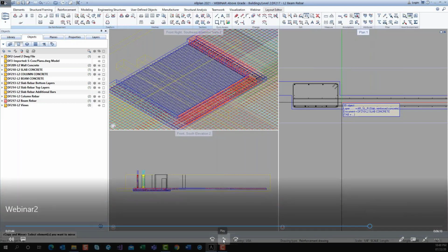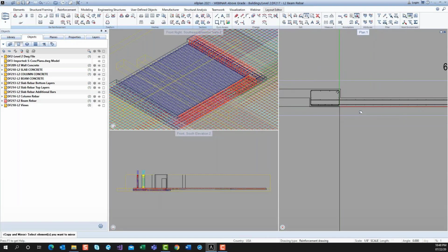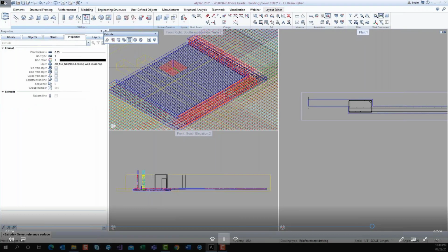So now, as I said, the contractor was called up. He says, you know what, Dave, sorry about this. It's either I've got a crane opening going in, or I have an opening in this slab. What can I do? Well, if it was the area reinforcement tool, I would have the ability to add the opening after the fact. But because this is our general tool, I'm going to show you, I showed you the trim bars command is trimming on a line. I'm going to show you how we trim to an opening, all 4 layers of steel in one shot. It's one of the very rare instances I have seen a software do this. I've seen other softwares try and attempt this, but this is on general rebar.